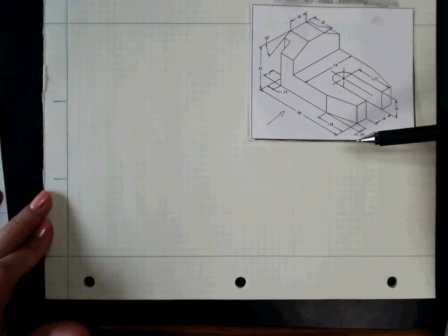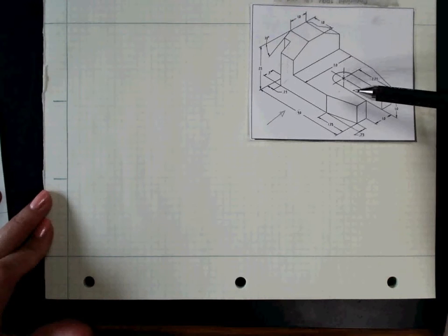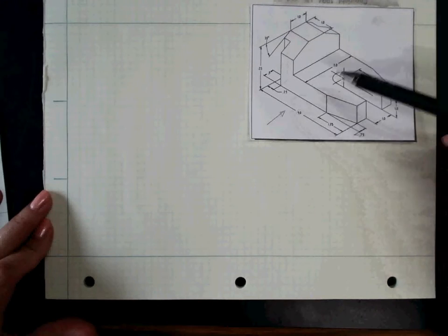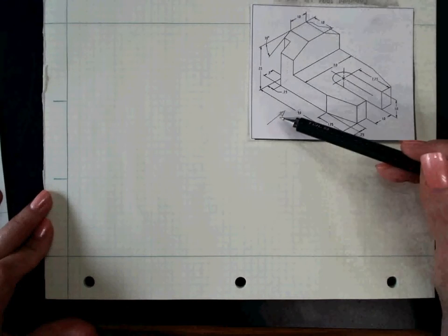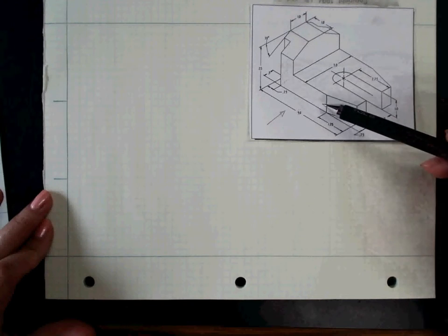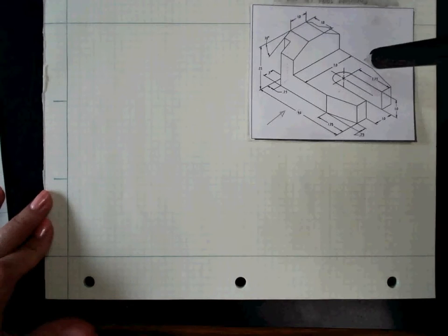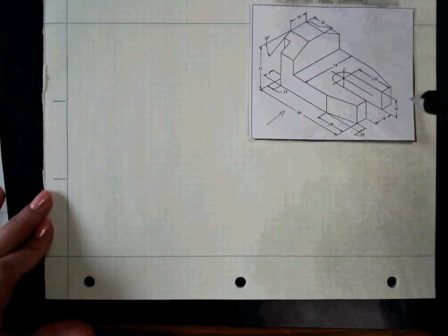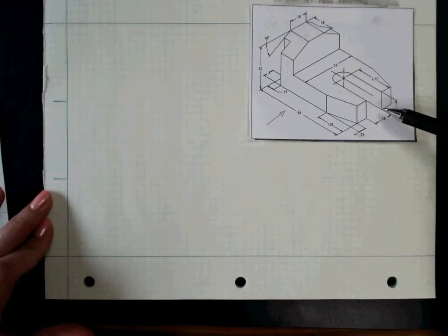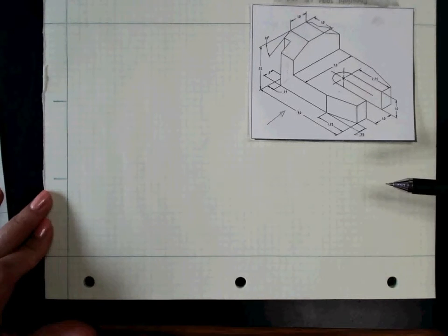Looking at it, we can see that we've got a good chance, in fact we can, communicate everything about this object using a front view, a top plan view, so a front elevation, which is just the elevation of this view of this side here, a top plan, which means looking straight down. If we had this object right in front of us, we would be looking straight down, and we're just going to draw a plan view. And then we can fill in the details with a front elevation, so an elevation looking from this direction.